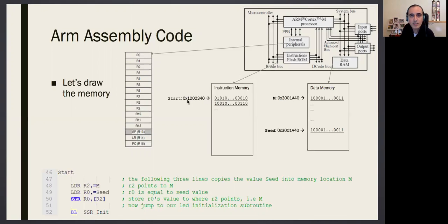Be careful, this is hexadecimal. So these are hexes. 1 hex digit is a nibble. A nibble is 4 bits. 8 hexadecimal digits, 32 bits. So each address in my system has a 32-bit value. That's why this is a 32-bit system. We'll get there. So it started to write my code starting from this address.